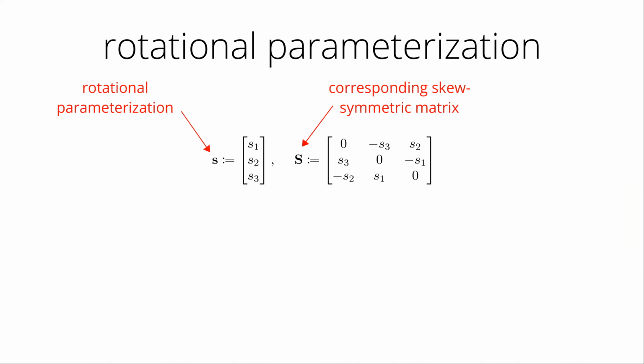The state of the filter will be the object's position, orientation, and the corresponding velocities. The position is easy to incorporate into the state vector, but the rotation is not as easy due to the manifold nature of rotation matrices. There are a lot of different attitude parameterizations like quaternions and Euler angles. Any parameterization is going to require modifications to be made to the unscented filter.